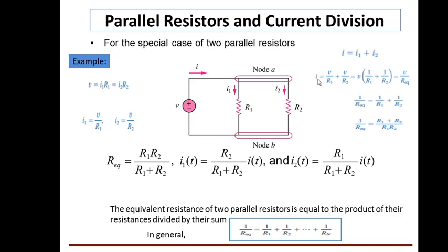From this expression you see, into I into 1 over R1. That is a formula, right? That is I, V by R. Here R is R1, right? So what is the V here? R equivalent into I. R equivalent is nothing but R1 R2 by R1 plus R2 into I into 1 over R1. R1 R1 cancel, the remaining is this one. So that means this first current, you can say I1, in terms of total current, is equal to R2 by R1 plus R2 into I.